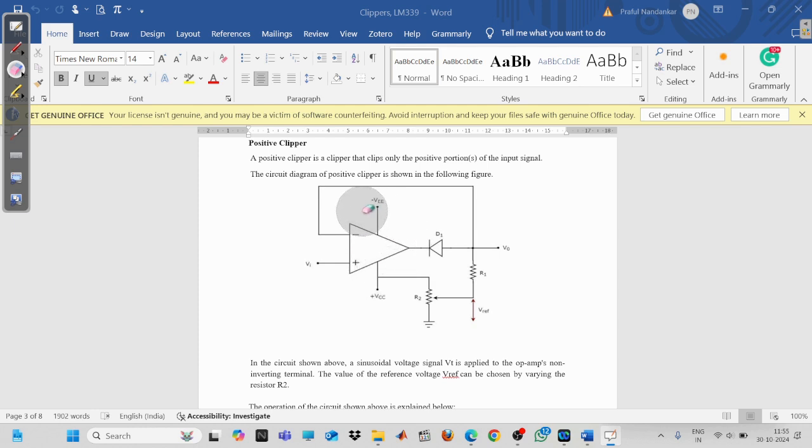This IC requires a dual power supply, and as you know, the first stage of the operational amplifier is a dual input balanced output differential amplifier. So basically, to bias your transistor, you will require two voltages. That is, you can say this has the minus 15 volt and the plus 15 volt. So this one is the operational amplifier. These are the biasing voltages.